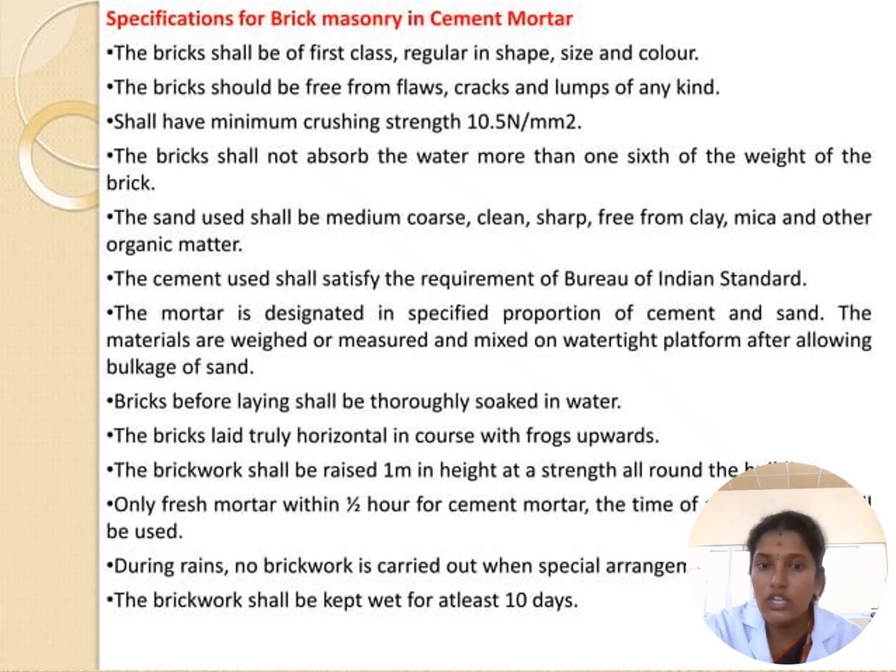After that, cement should satisfy the highest standard. After that, it comes to the mortar. In the specified proportions of cement and sand, the materials are properly weighed and measured and mixed on proper platforms, right? After that, the brick laying. Before the brick laying, what do we have to do? The bricks shall be thoroughly soaked in water. After that only the brick laying starts.